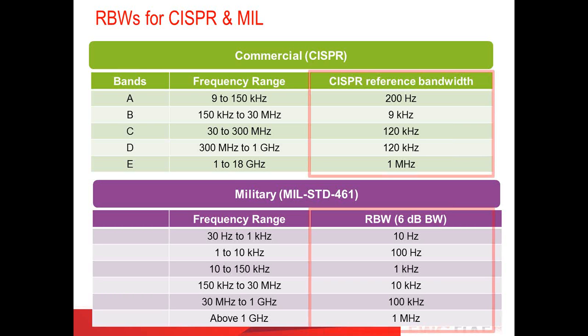So the takeaway here is, to get the best possible sensitivity, you want to use as little attenuation as possible. You can also use the preamp in the opposite fashion. The preamp is going to improve your signal-to-noise ratio. Since the signal level stays constant, that forces the noise floor down.